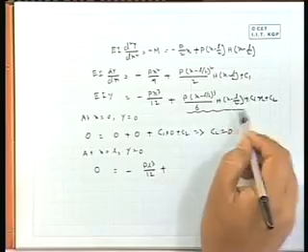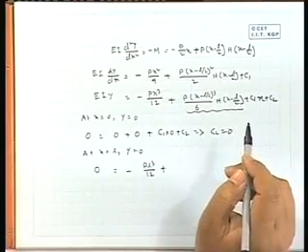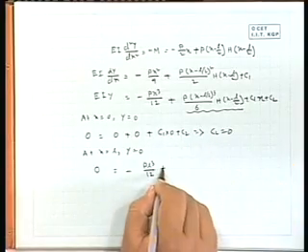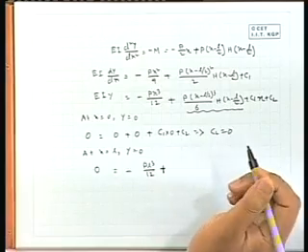Now, if you take the right end at x equal to L, y is again 0. Here it will be 0 equal to minus P L cube divided by 12 plus, in that situation this term will be activated because the unit step function value will be 1. That is the important point.